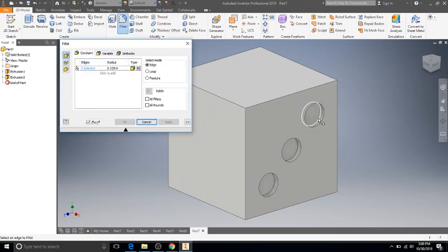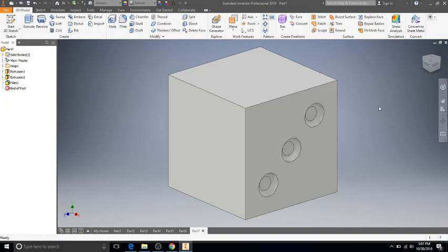And I want you to round those edges. To do that, you're going to use fillet. So if you notice, if I click right now, it's not at 1.25 inches. The fillet is not the right size. It's a little bit too small. We want it to be nice rounded. So click in there and make it 0.25. Okay, and then you can just click and add any additional shape that you want. You could save that for the very end and just do it for all your faces if you like. But anyways,